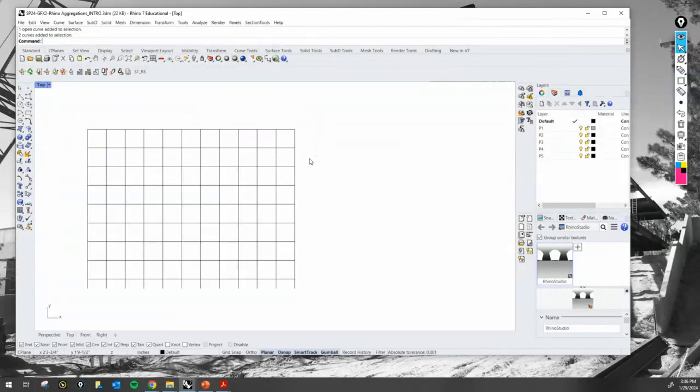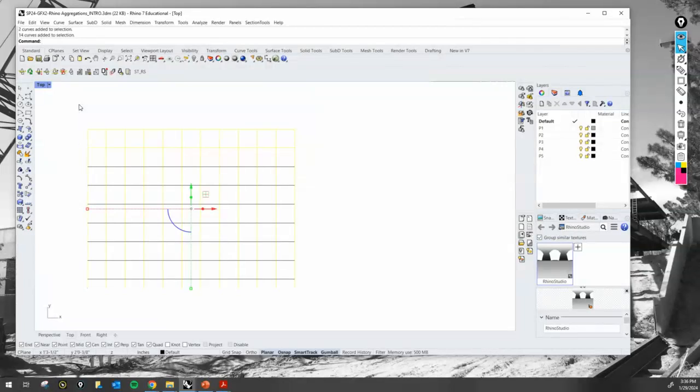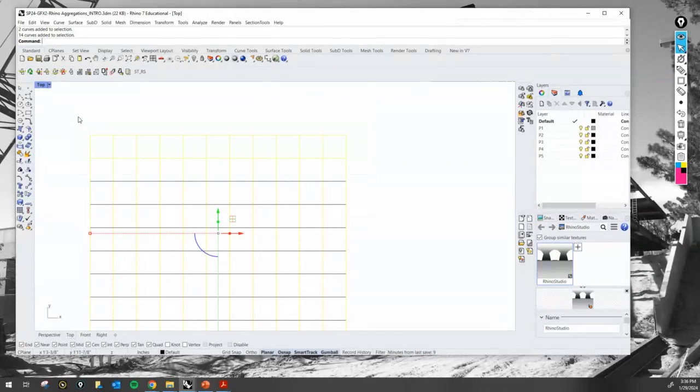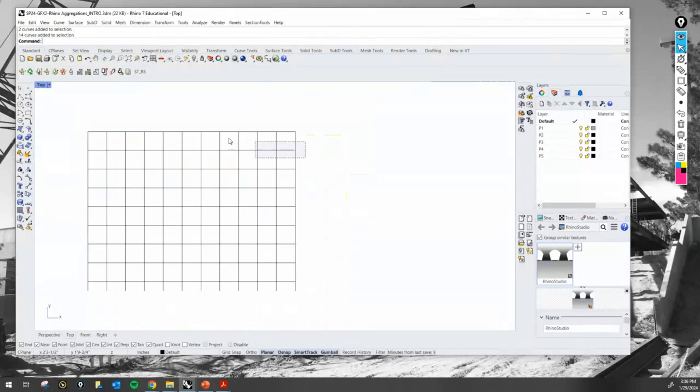Now if I repeat that, but from the bottom right corner to the upper right corner, notice how my selection box is now dashed rather than solid, right? So that's solid. This is dashed. And what happens now? Anything, regardless of whether it is fully enclosed or not, that the selection box touches will be selected. And that's what happens.